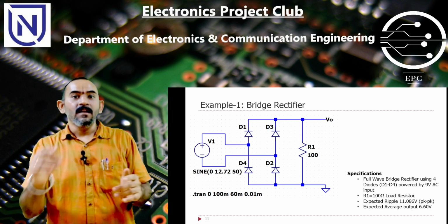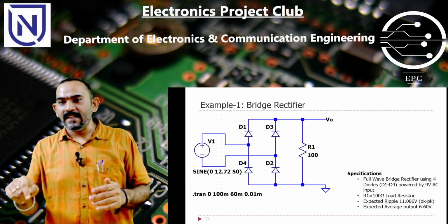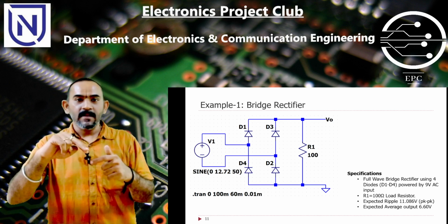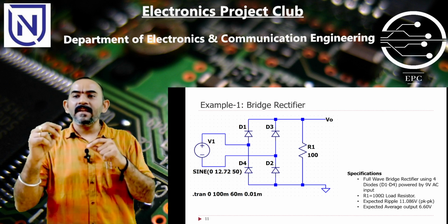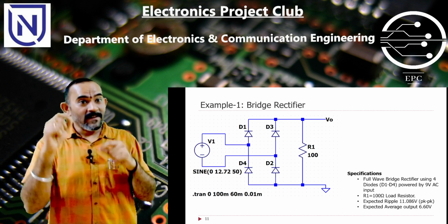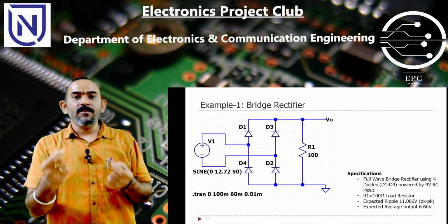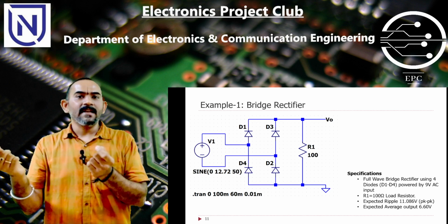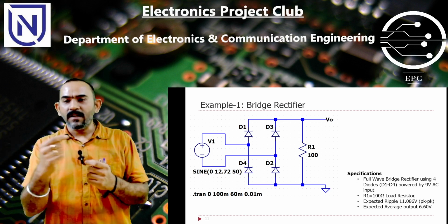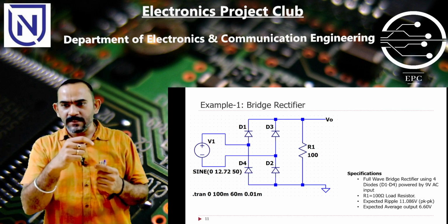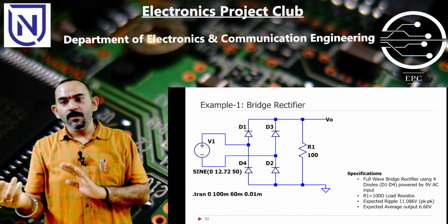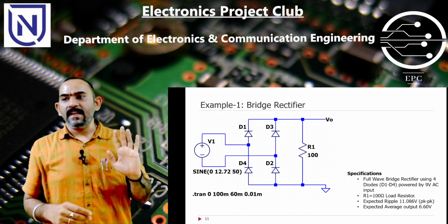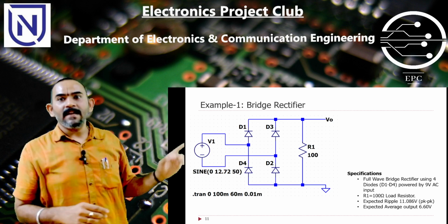What could be the fault? You need to check one condition at a time. Check whether the diode is mounted properly, with anode and cathode correct. If it is proper, check whether the diode is working fine. How do you check the diode? Use the multimeter in diode testing mode and connect it across anode and cathode. As you connect, it should show a VF drop across it. If you reverse it, it should show open circuit. So you check that, and then you identify the case. This is how we proceed.